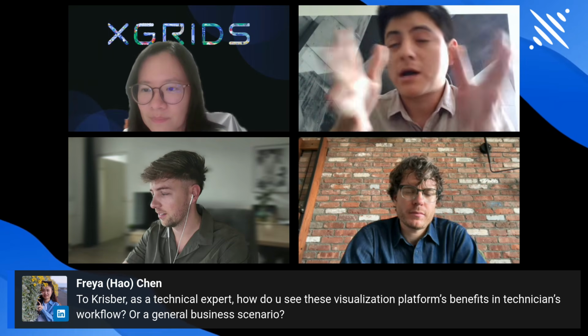Yeah. Thank you, Freya. So yeah, I come from the scan to BIM industry before I focused entirely on the visuals. And when you are doing modeling work, you need to double check the data that you are representing. So you have to go to 360 photos that we capture with the LiDAR scanning, which are usually in low quality with colors that don't match with reality. So having a Gaussian splat model that replaces a virtual tour and also has a structural geometry that can be overlaid to the Revit model or LiDAR model is a game changer for me.